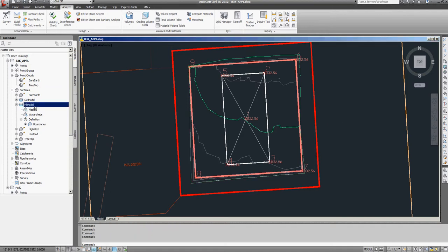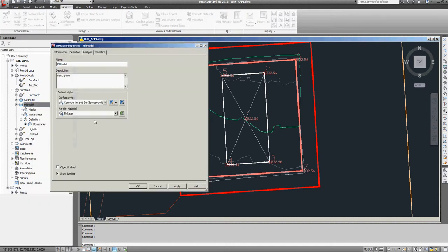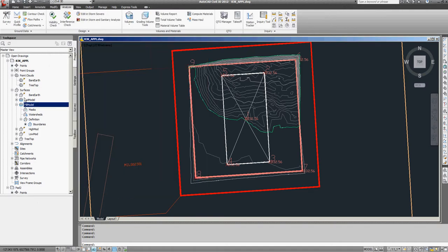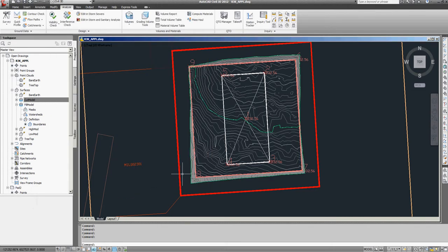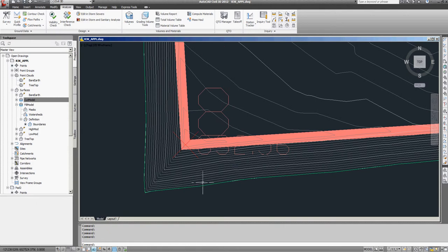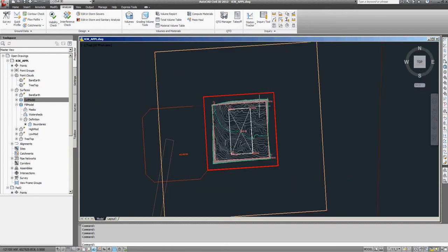And so then, as I said, we could for example change the display as well to increase the number of contour lines on both the cut and the fill model, so that you now have a very nice diagram of exactly where we would have increasing amounts of cut required. So the edge of this lease, for example, here sits in 1.8 meters of cut, coming out to 0 meters of cut where it intersects the land.